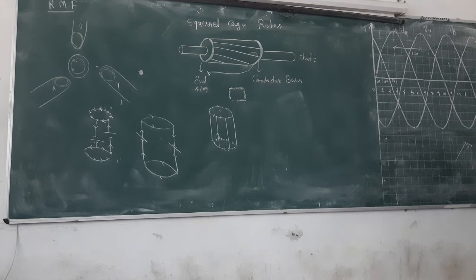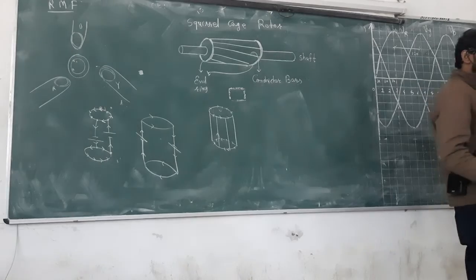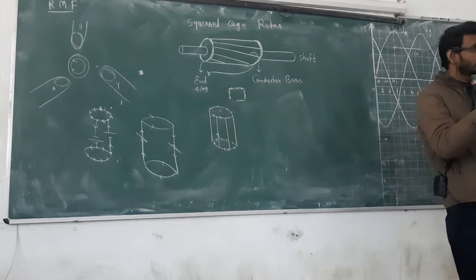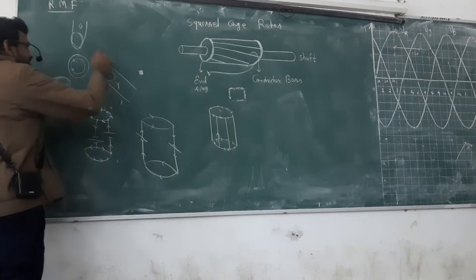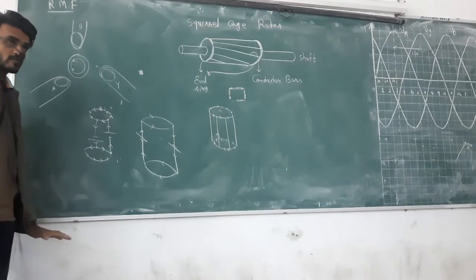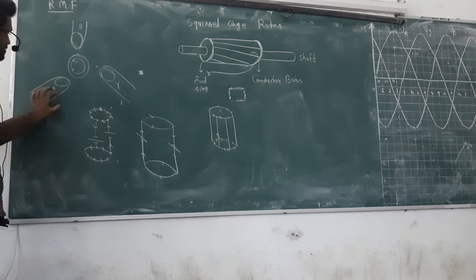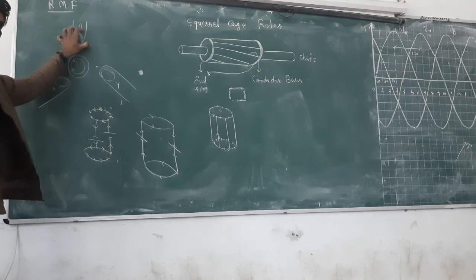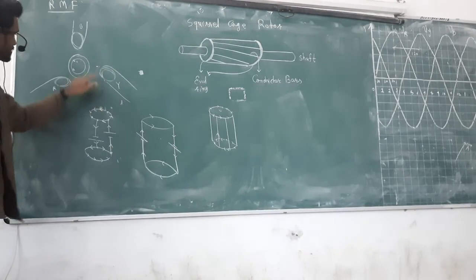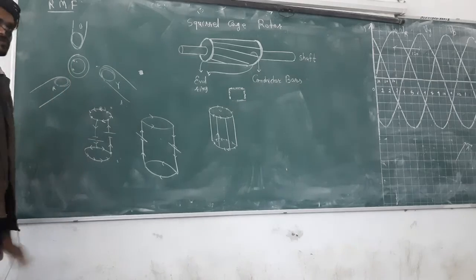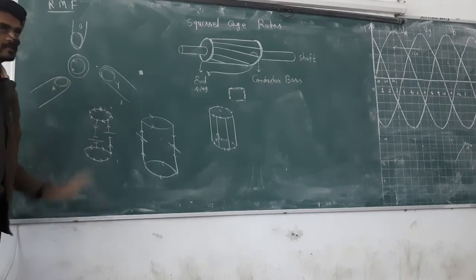We have also discussed that if you do not have a permanent magnet, if you have 3 coils and give a well-defined supply, with all 3 coils oriented 120 degrees apart, there will also be a rotating magnetic field. So now you put 3 coils in the rotor, give a 3-phase supply, and automatically there will be induced EMF inside the rotor.